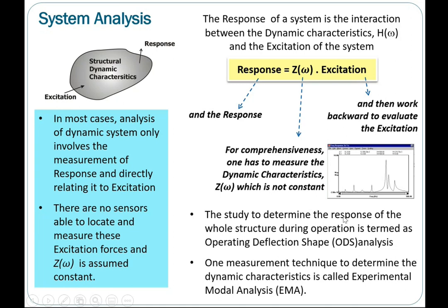To determine the response of the whole structure, when we say the whole structure, not only one point at the bearing housings of the machines. Here we are referring to how this entire machine is vibrating, moving, or deflecting during operations.